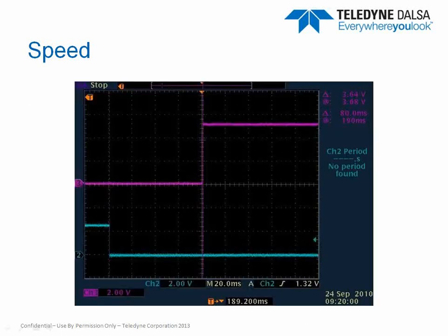As an example, when somebody gives me a really, really critical inspection time, from the point that I get a trigger to the point that I'm responding to the computer, I always like to take a scope and measure. So here's an example of a trigger signal to the output, and the customer wanted to be under 200 milliseconds for this processing time, and I ran these tests hundreds of times to make sure that with all the conditions, from trigger to the time that I sent a signal to the PLC was under 200 milliseconds.